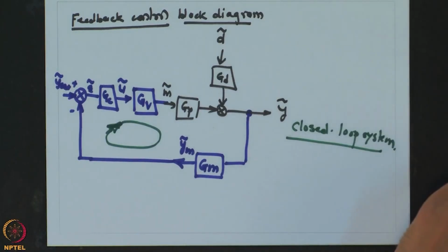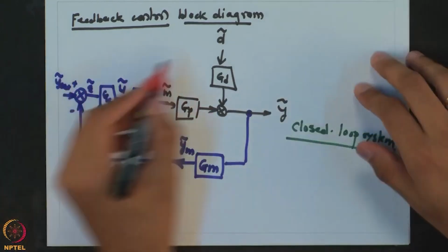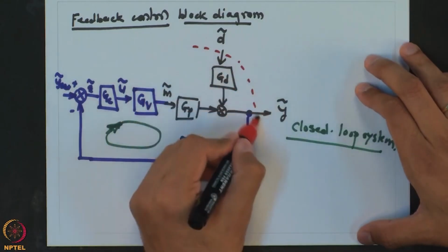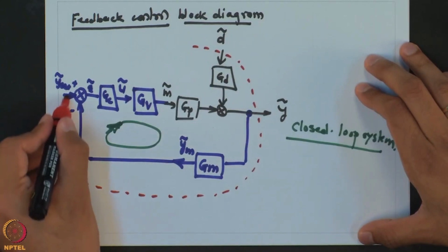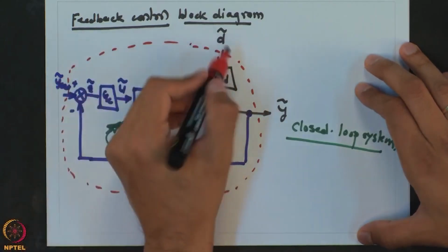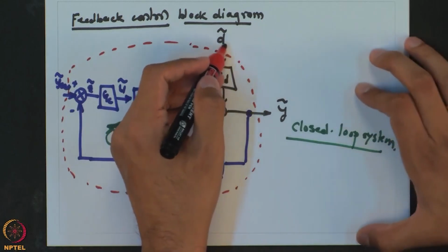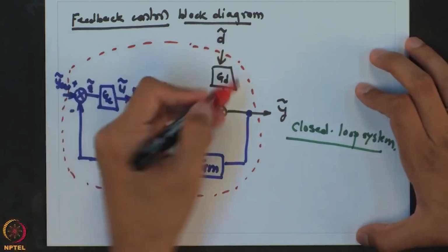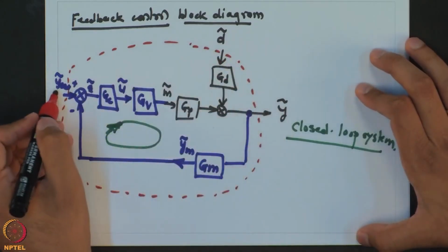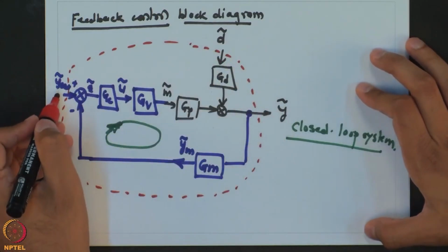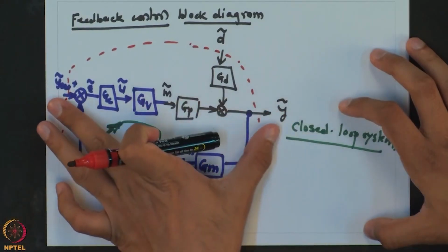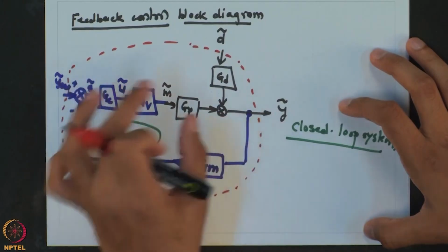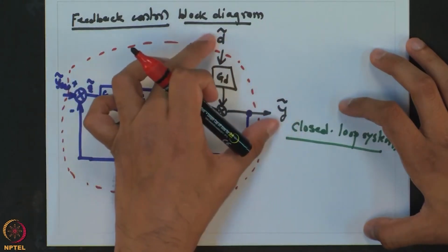And in terms of our earlier representation, this block diagram represents the installation of the feedback system, so that you can have some changes in the disturbance. Whenever we are trying to reject the disturbance, the controller will take an action, and then you may want to change the desired value, a set point value, and accordingly you want the output to change in response to that. So, you can have a servo problem when these two variables are in play, or you may have a regulatory control when these two variables are in play.